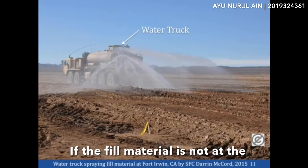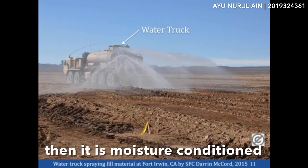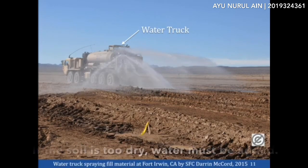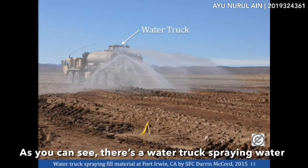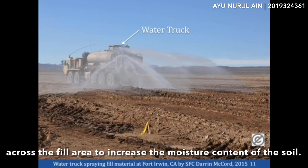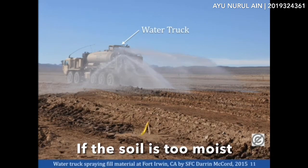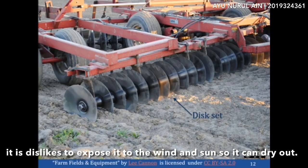If the fill material is not at the optimal moisture content for compaction, then it is moisture conditioned. If the soil is too dry, water must be added. As you can see, there's a water truck spraying water across the fill area to increase the moisture content of the soil. If the soil is too moist, it is disked to expose it to the wind and sun so it can dry out.